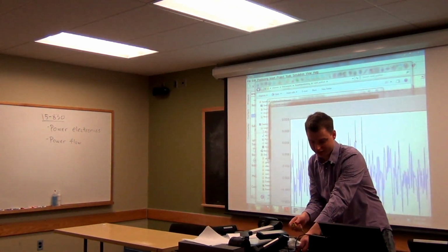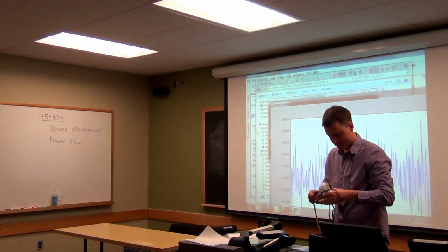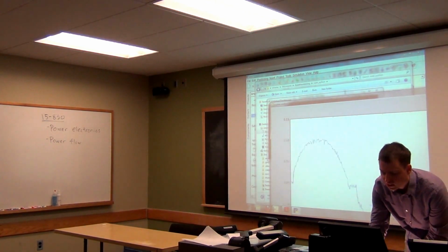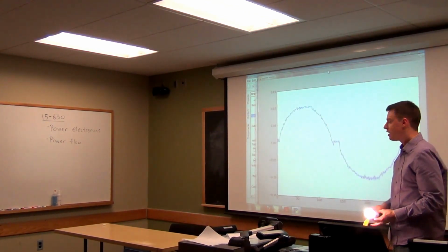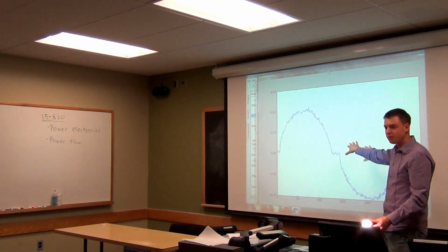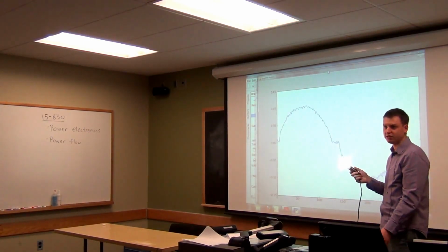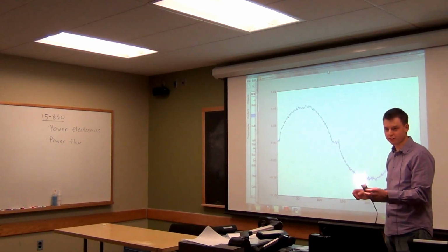Okay, so this is the hard drive again. Here is the light bulb. It looks a lot like the sine wave, and there's some noise, and there probably is some power electronics in there that might actually be shaping it something like that. But this looks similar to a rectifier that basically has much less capacitance, so it doesn't need as steady a voltage source. It can make use of different amounts of voltage.